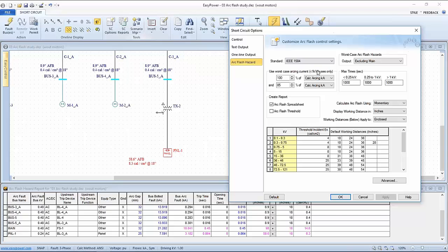According to the apps note, and I encourage you to download it from the website if you haven't already, called Calculating Arc Flash Energies for Low Voltage Circuits, it recommends that below 250 volts, we can actually limit the calculation time to something much less than 2 seconds.